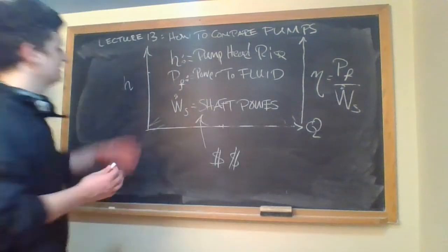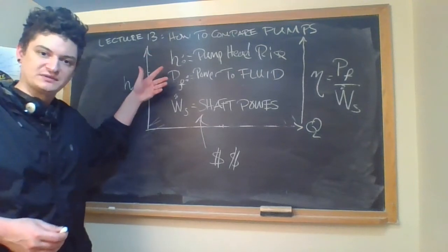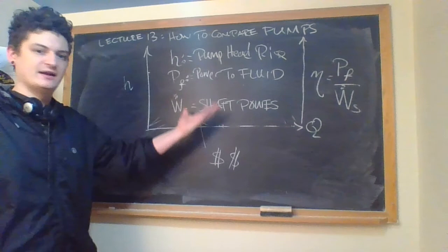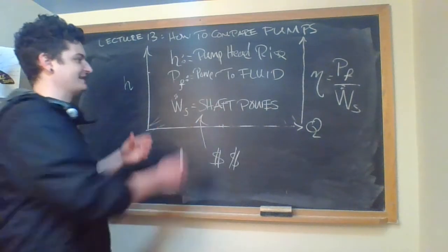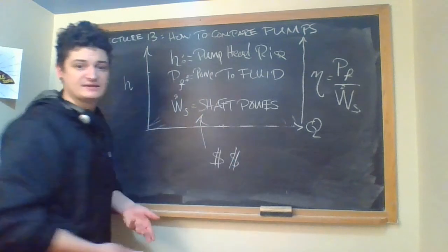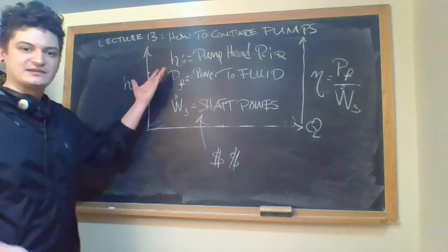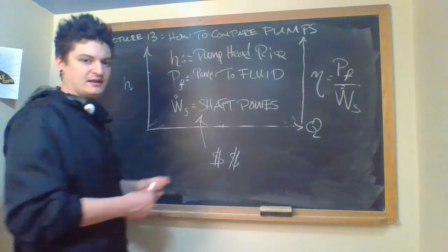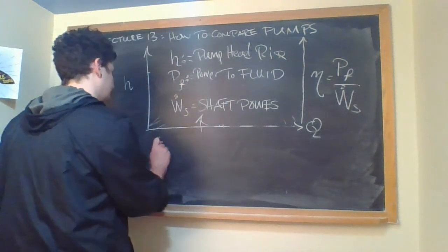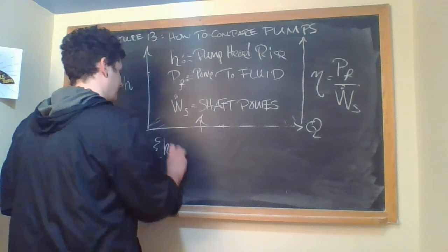So these are really the dependent variables that we care about when it comes to a pump. It's really how we evaluated any pump that we got: draw some plots on these axes and then look at the flow rates. But it was a combination of three things we always looked at. Those were the dependents. So we had head rise.